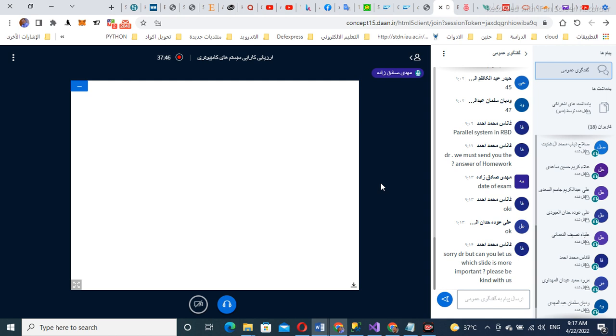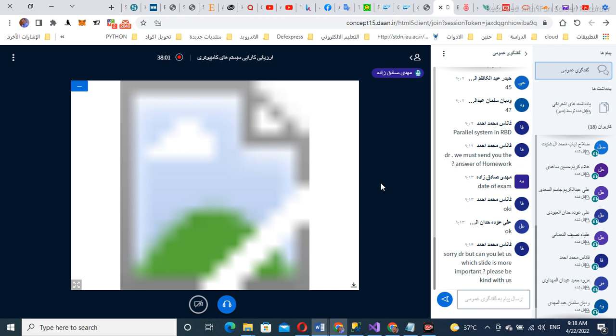So here you can see a comparison between exponential and Weibull distributions. The horizontal axis is time, the vertical axis is reliability. When time increases, reliability decreases. This means the probability of the system failing in its lifetime will be higher. But the reliability of the exponential is better than the reliability of the Weibull, as you can see.